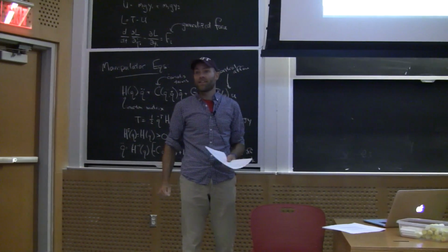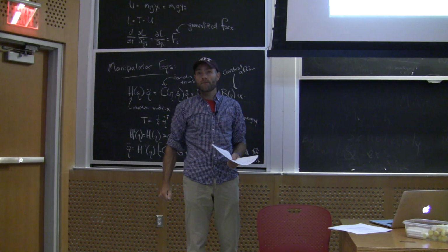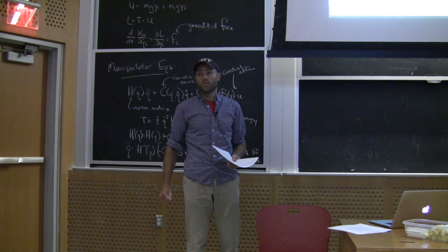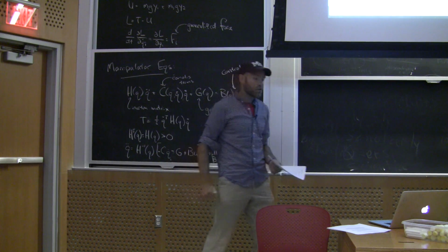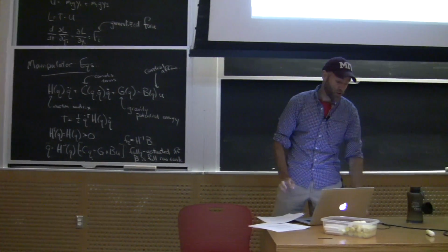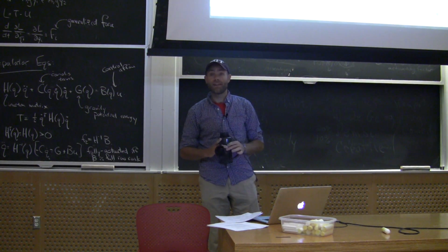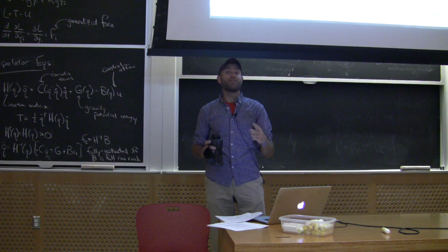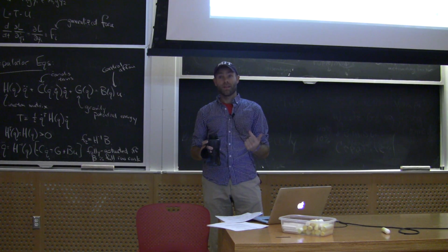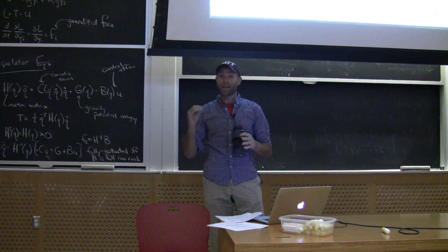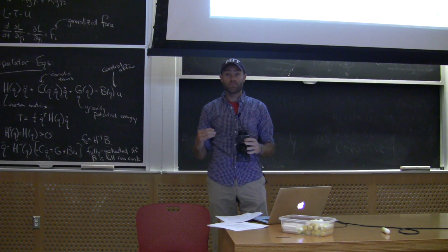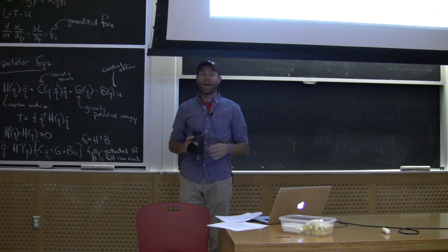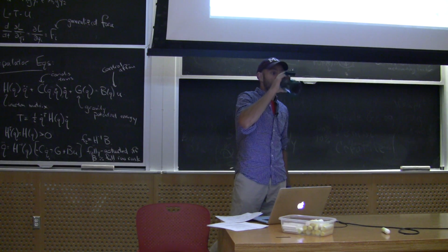Yeah? So you mentioned needing an actuator to fully control this at the other joint. Yep. But could you control it by moving the first actuator instead? So that is the topic of the course. Having not enough actuators means you can't instantaneously accelerate in arbitrary directions. It doesn't mean that you're necessarily very impoverished as a control system. It just means that you have to be more clever. I can't make this system look like an arbitrary linear system and apply linear control techniques. I have to think about F, okay? I have to do more sophisticated control.